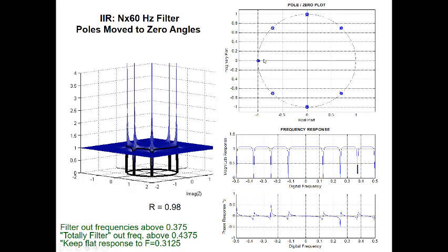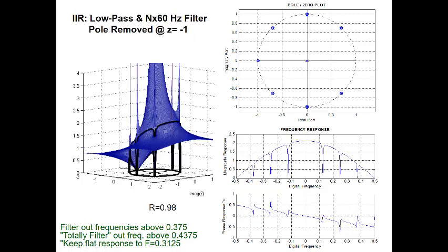Well, this one that's holding up the rubber sheet here, that's helping create the narrow notch here, but now we're saying we want to filter out, we want to remove some of these high frequencies. So the first thing we'll do is remove that pole. And let's drag it all the way back here to the 0 so it doesn't do much of anything else. And as happens with this technique, when you do something that seems fairly obvious and straightforward, it changes everything else.